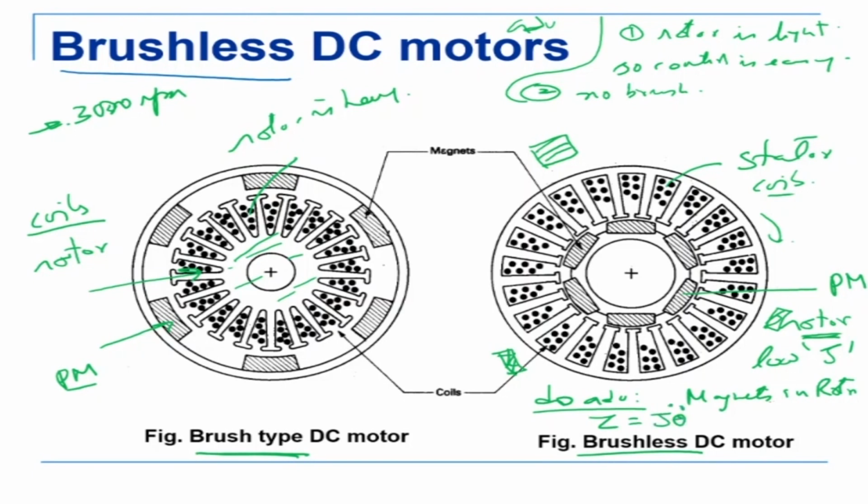So the torque produced by the motor is equal to J, which is the inertia, into the acceleration. If J is very, very low, because it's a very light motor, but the torque has to be high, then the magnetic flux, phi, must be very high. So it basically means that you need very strong permanent magnets.